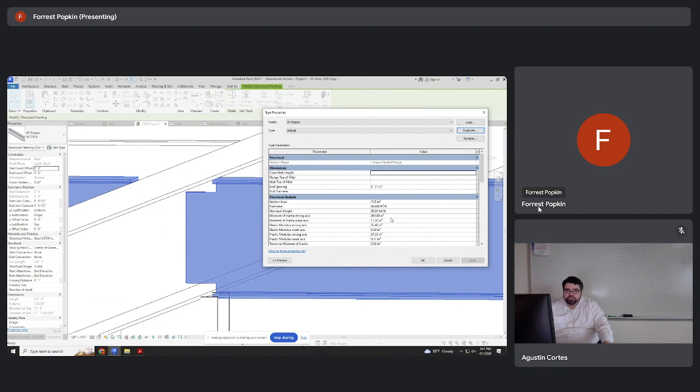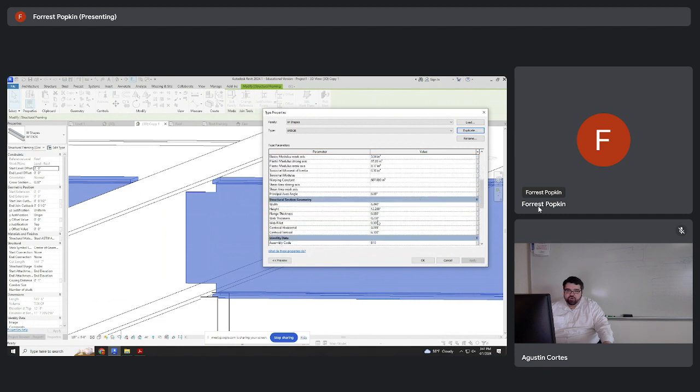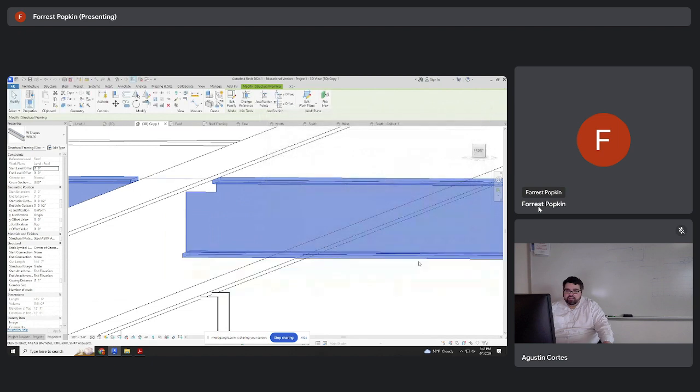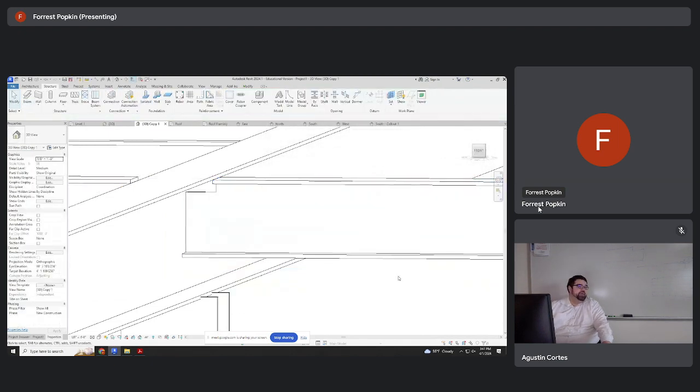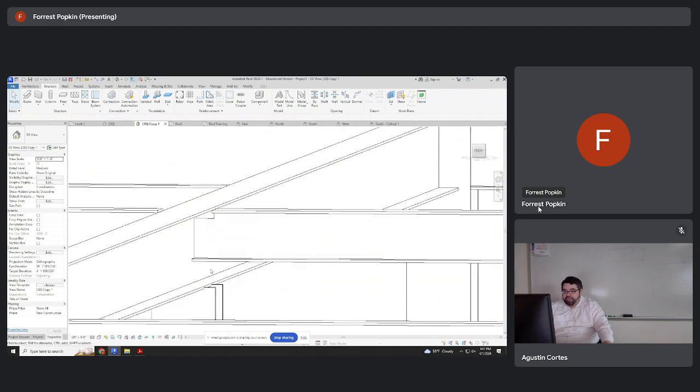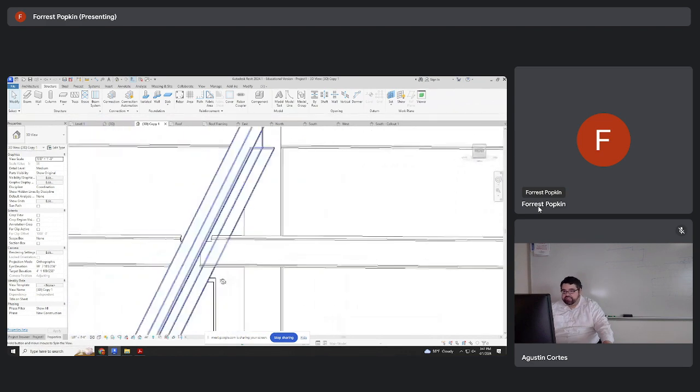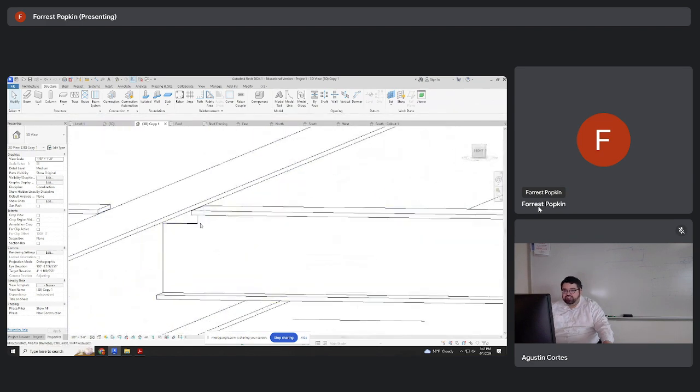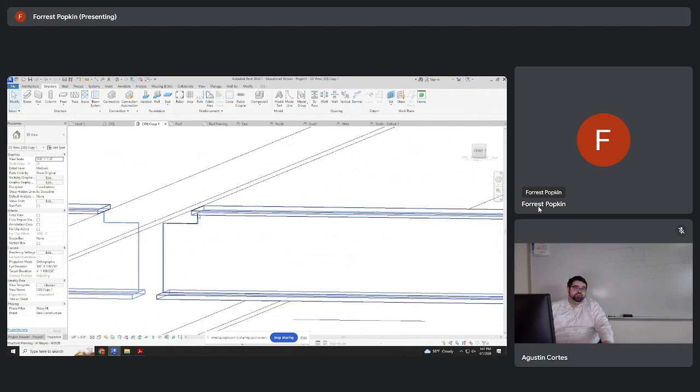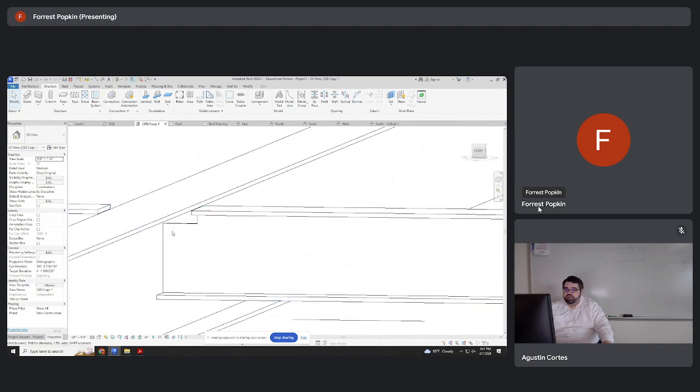Now, of course, the issue with doing this is that you're kind of guessing what all these things are when you really shouldn't be doing that. But for the sake of this demonstration, if I were to make this, say, 8 inches, you'll see that's what happens. The benefit of doing the coping is that it automatically knows where to cut. So you'll see what was cut down here is now flush. So what's happening? Well, because my beam is not as deep as my girder, I only notch out the top part there. You following? Okay.